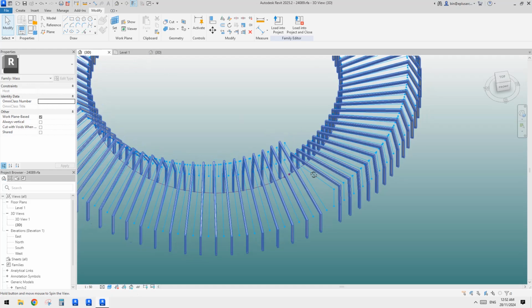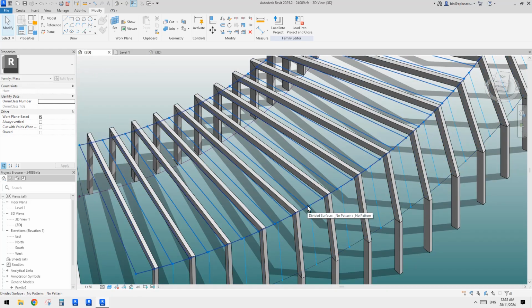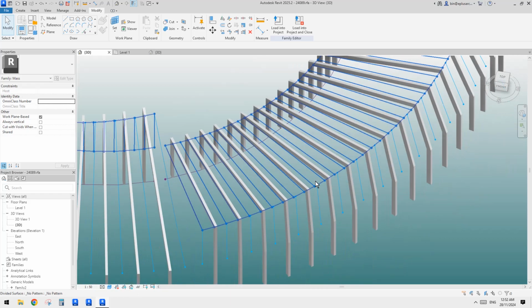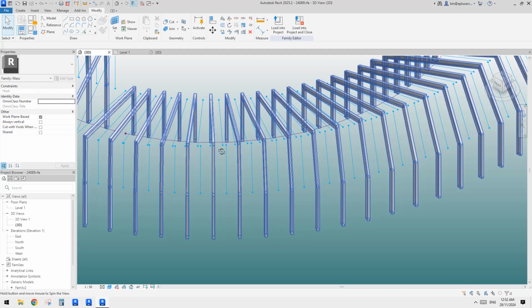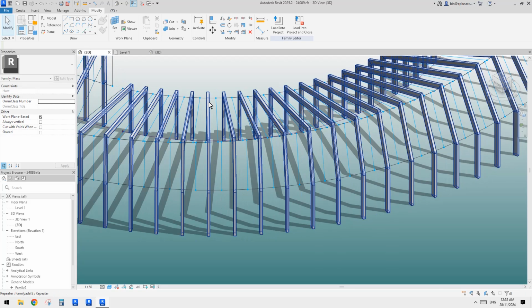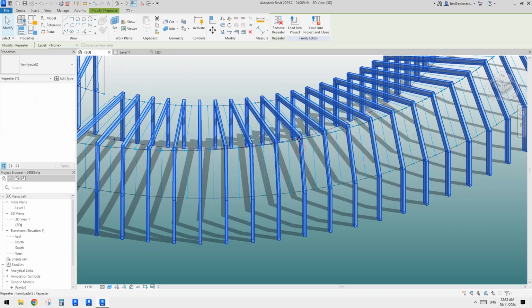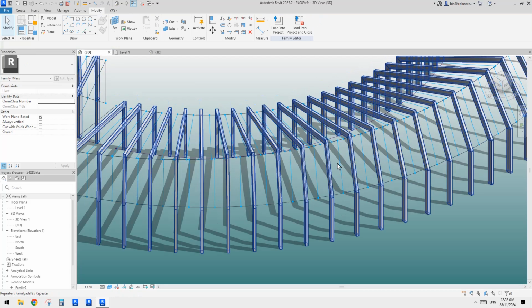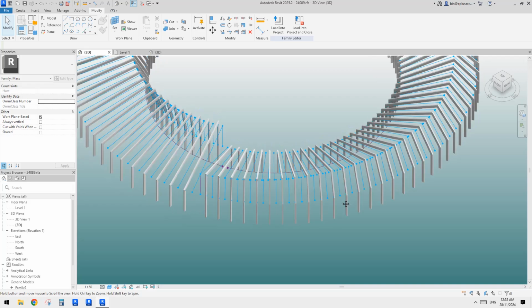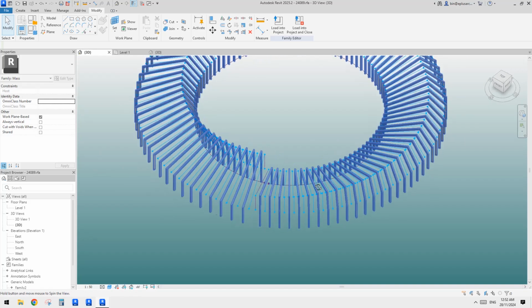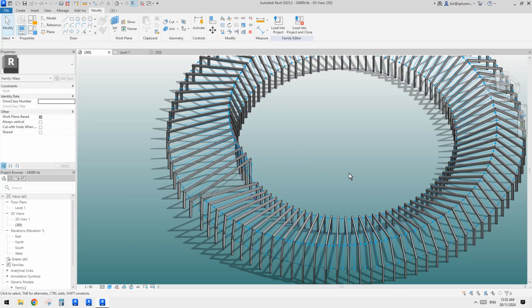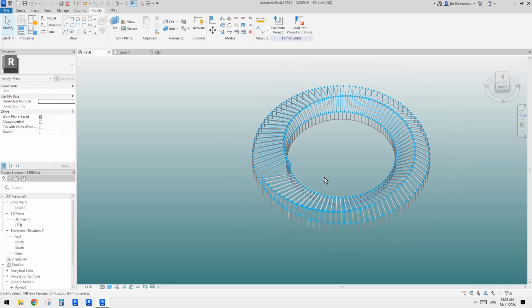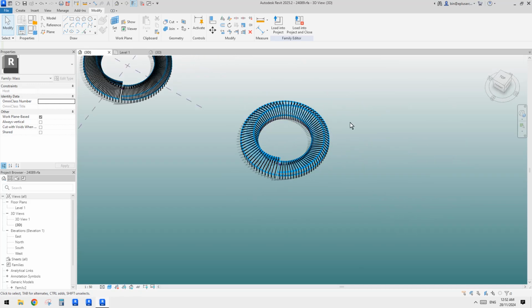So in this one, it doesn't matter where the nodes are, it always places at the point that aligns with point 1 and point 3, but just uses the height of point 2. Right, so this is the third method. I think this is also quite good because we don't need to do all the reference planes, and it can be used for more crazy shapes.